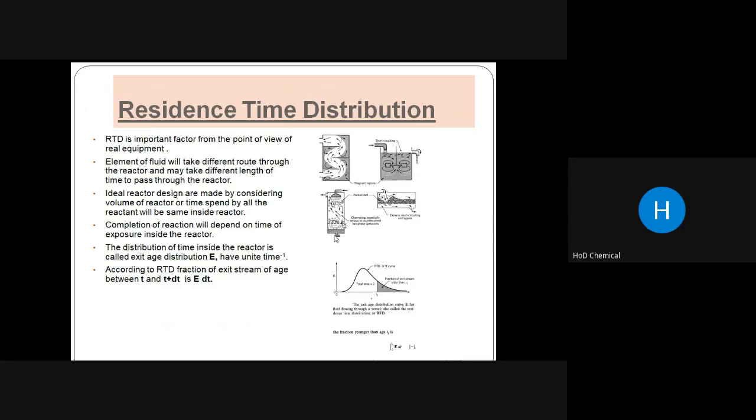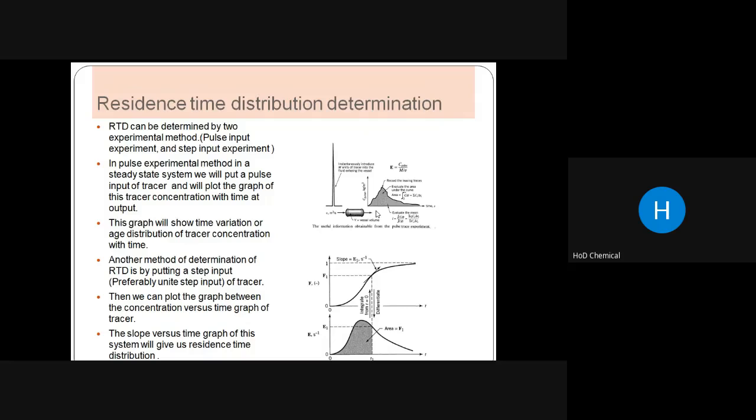Okay, so those are the reasons any reaction in the reactor can deviate: stagnant positions, short circuiting or channeling, non-uniform mixing, contacting patterns. All those factors can happen in reactors. We can do this on ideal reactors, so it's not easy to determine the residence time distribution.